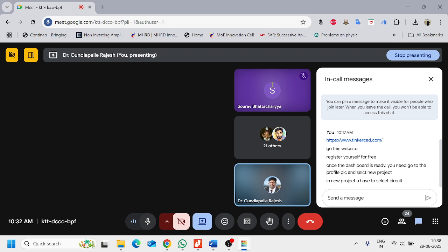We stop editing. Pin mode out, LED 1, so 12 pin, so the pin is not connected properly, right? I have reversed the connection, sorry. Positive has to be given, but I have given the negative. That was the reason why it has not worked. Now let us run the simulation. Yeah, now see, yellow is also glowing.